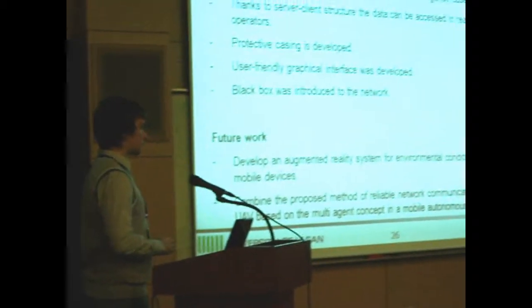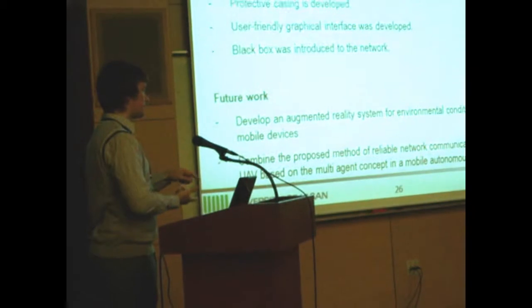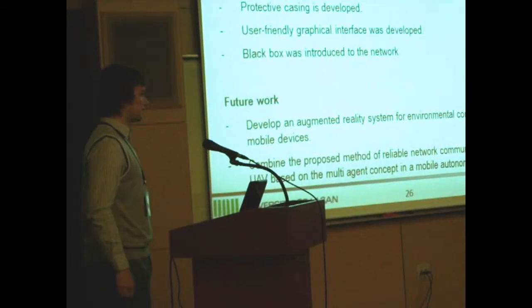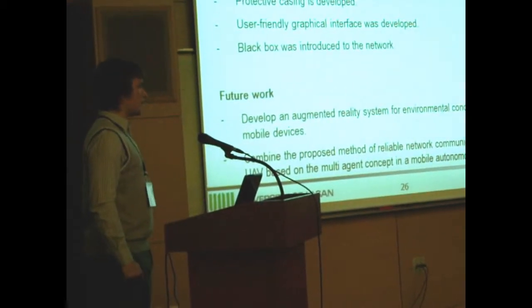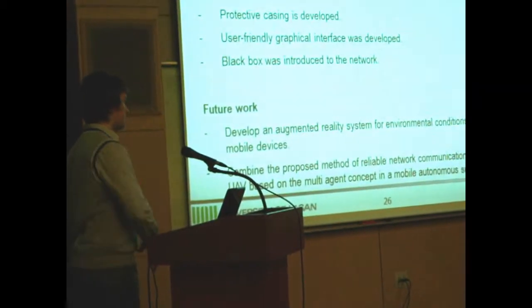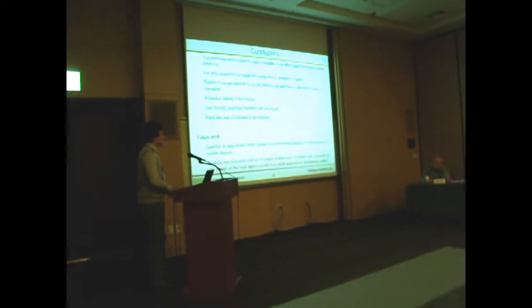And when you collect the data in your database, is the database routine itself based on Zigbee communication or? The database server has an internet connection to share its data, and we use a USB dongle which can connect to the Zigbee network. And this dongle uses RS-232 serial communication. Interesting. So you're using MySQL over there? Yes, I'm using MySQL, and to program microcontrollers, I use plain C language.